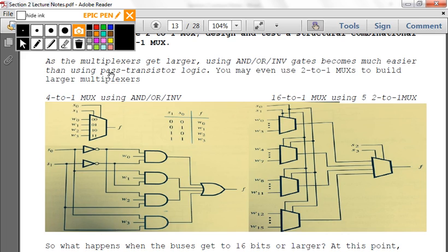This is something that happens in a 32-bit MIPS where we have a fixed instruction length and are trying to choose between two values. So we have two 32-bit values. What do you think we would do? I want a 32-bit value on the output. Here's some design. It's not just memorization. Now we're actually designing something.